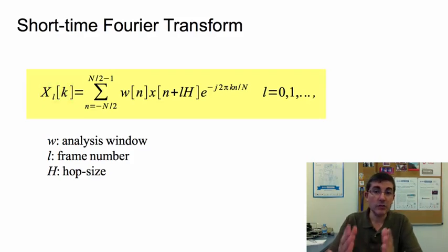To emphasize the idea of zero-phase windowing that we have already talked about, from now on we generally specify the time index to go from minus N over 2 to N over 2 minus 1. So it's always centered around 0. We don't have any phase changes, and we don't have any kind of shifting in time and therefore in the spectrum.